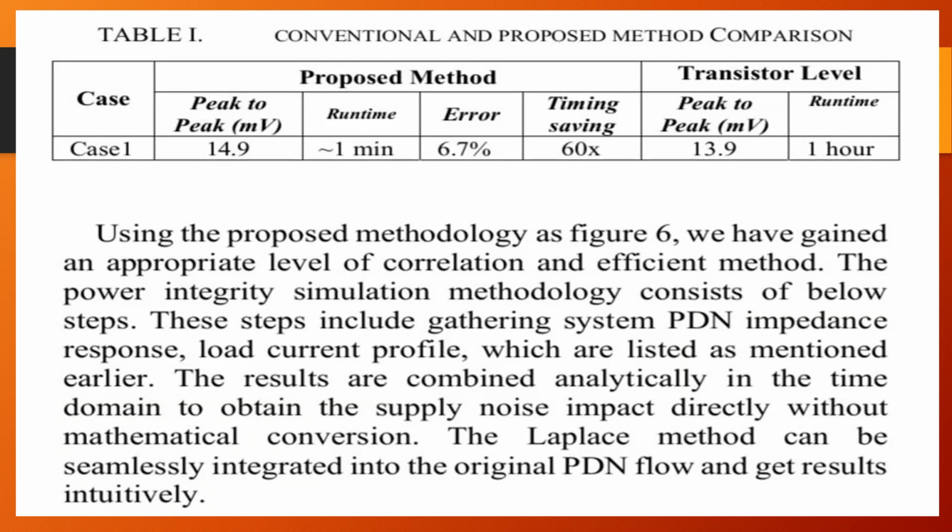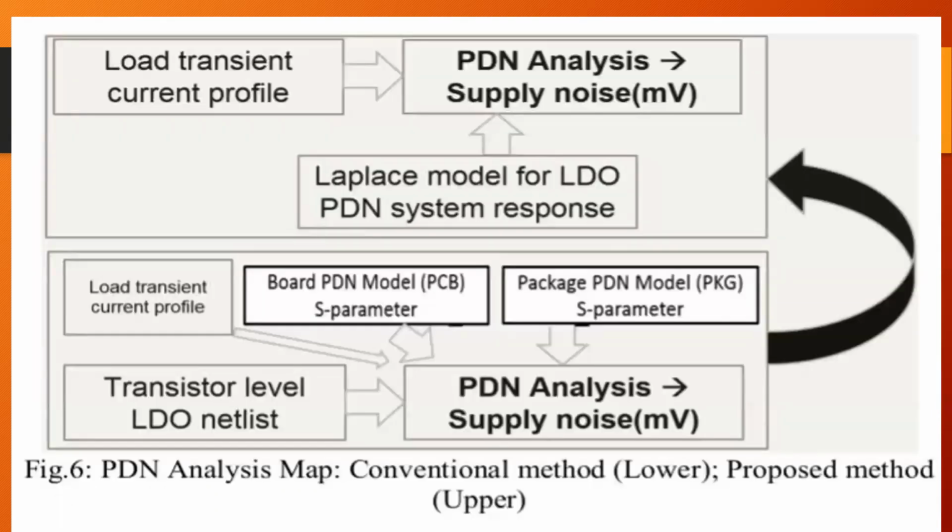The results are combined analytically in the time domain to obtain the supply noise impact directly without mathematical conversion. The Laplace method can be seamlessly integrated into the original PDN flow and get results accurately.